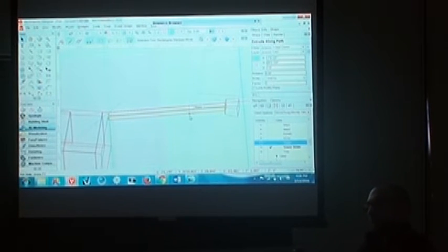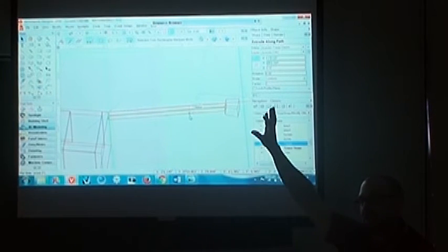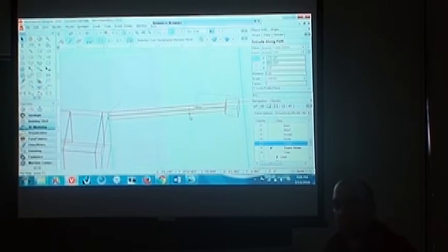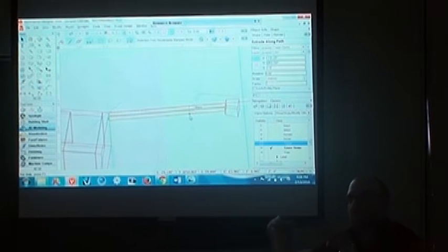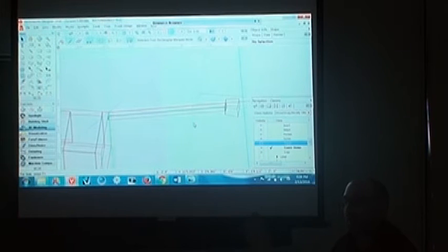extrusion that is tapering. It's tipping in both directions at the same time, but staying the same five inches, the same cross section, but it's following that. So the structure itself isn't tapering, you just have these weird angles at the base and the end, right? So I could then take this, create a drawing, and dimension what those angles are, and then I would know exactly what I need to cut if I were going to make that piece in real life, right?